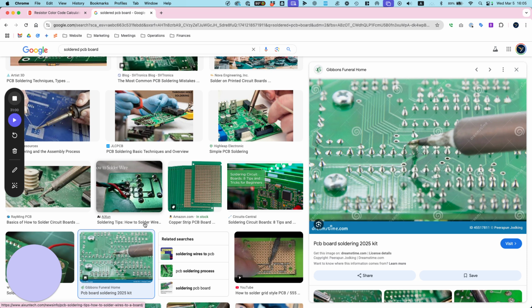You place that right against the molten solder, once you melt it, that is. Okay, so let me demonstrate here. I'm going to melt this. What do you call that gun? A solder sucker. So right here I am melting. You see?